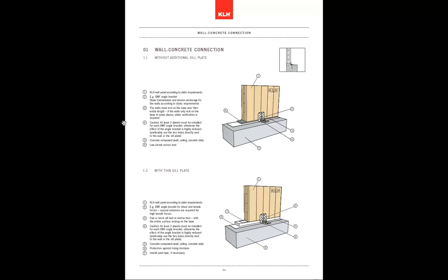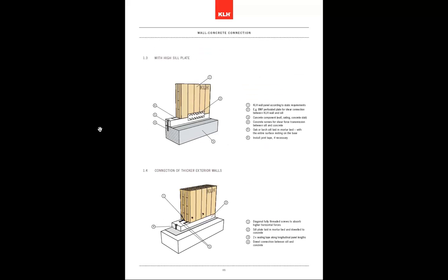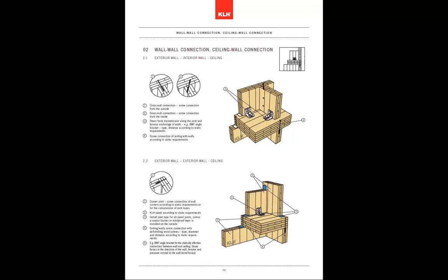So here are some simple details at the base, how you fix the CLT to the concrete. I'm not going to talk through all of these. You can have a look at them yourself. But some more base details, and you can see, as Ollie mentioned, some of the different kinds of fixing plates that you use, and these very, very substantial screws, which they drive in with an impact driver.